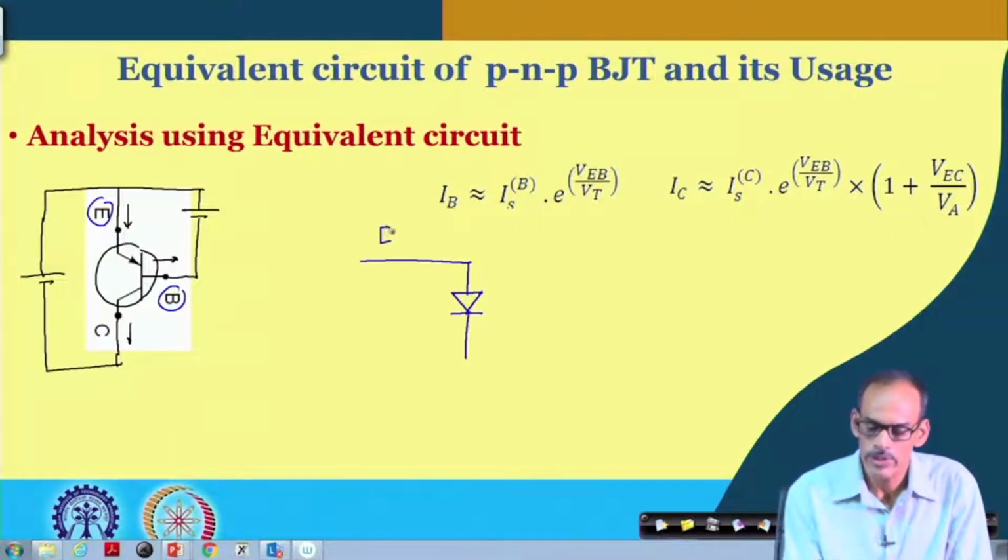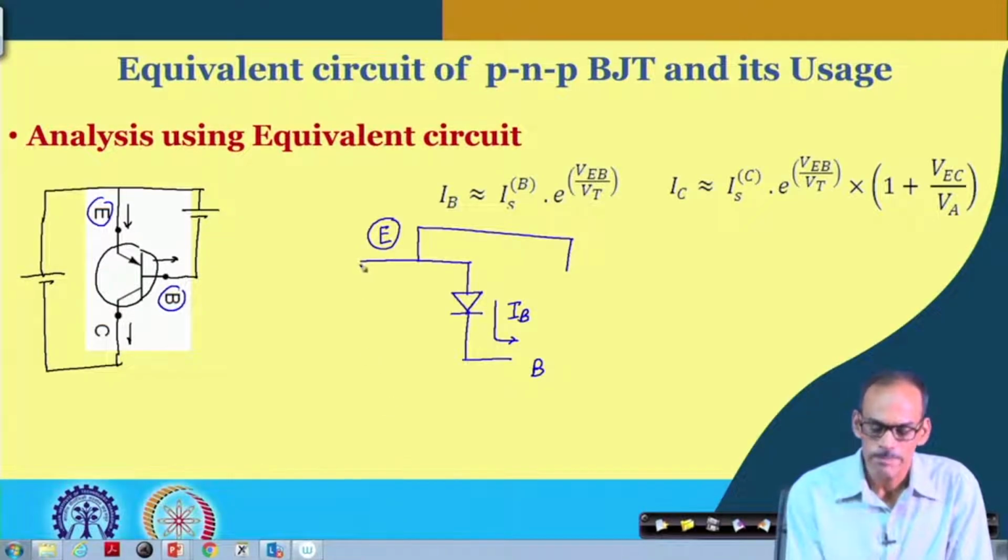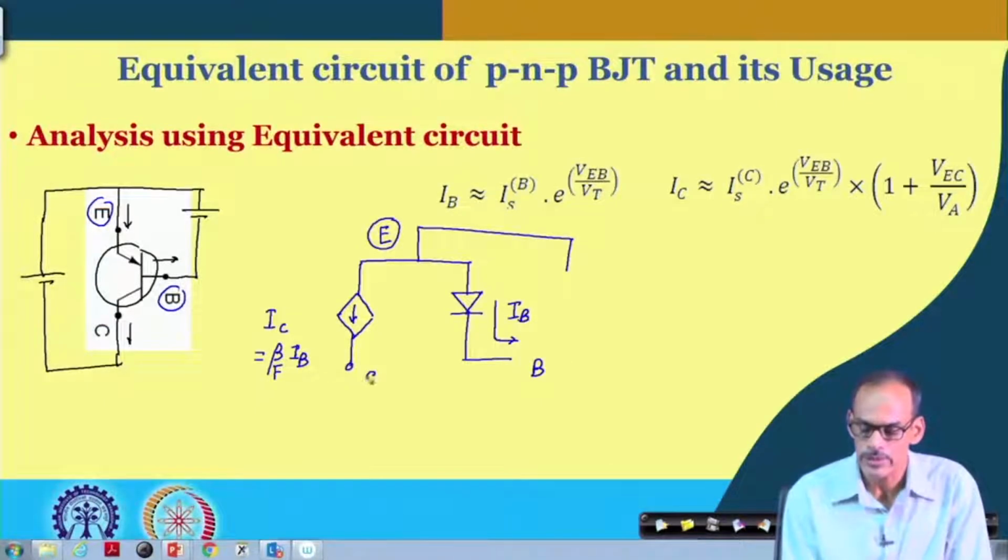We do have the emitter terminal and we do have the corresponding base terminal. So, we can apply the corresponding external bias, and then we can find what is the corresponding base current flowing. And then from the emitter to collector, we do have the collector current. That current is a kind of linear function of the base current. So, we can say that this collector current is beta of the transistor times whatever the I B we do have. So, that is the collector terminal current.